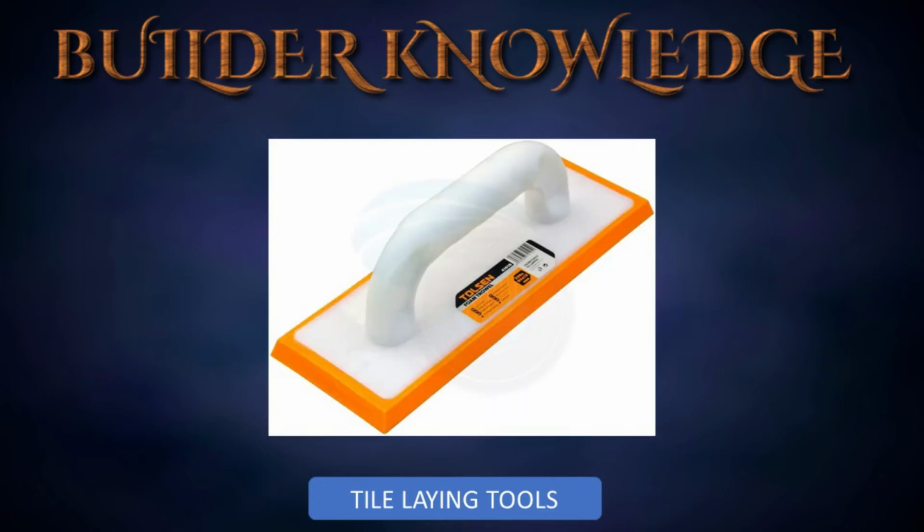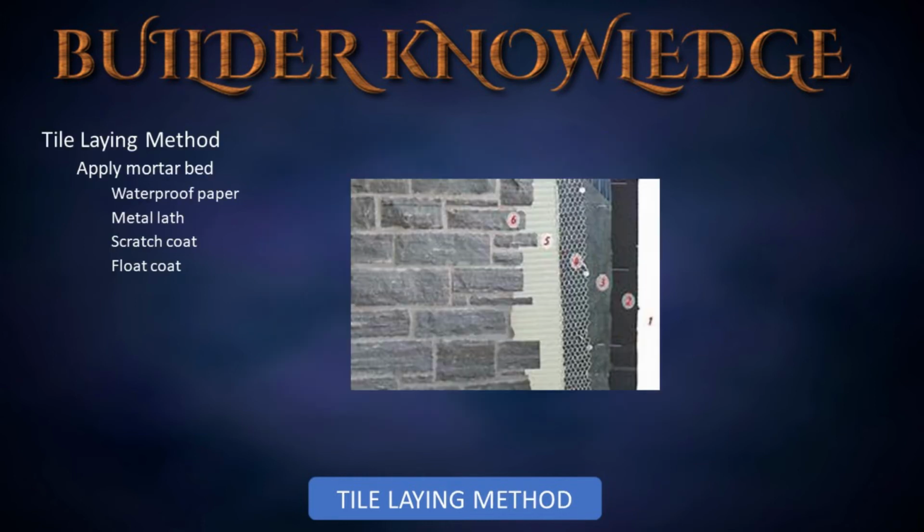The rubber surface trowel is used to force grout into the joints of the tile. Remember what Petty Officer Google said about sanded and unsanded grout use. Now let's cover a tile laying method. I refer to this method as the old school method.